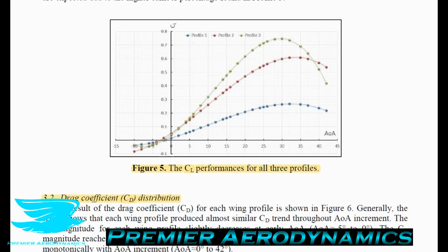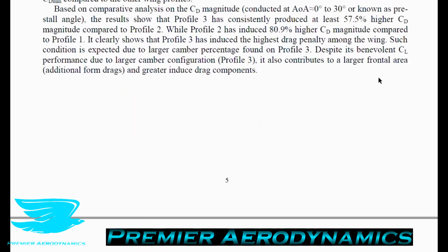So, for example, in NACA 0021, I think at like 100,000 Reynolds number, the stall angle of attack is like 13 degrees, something like that. It's very low. Whereas these ones, the stall angle of attack is around 30 to 35 degrees. So you can go to a much higher angle of attack, and that means it's more stable. You can have safer margins. So that's how Zimmerman airfoils are different to regular airfoils.